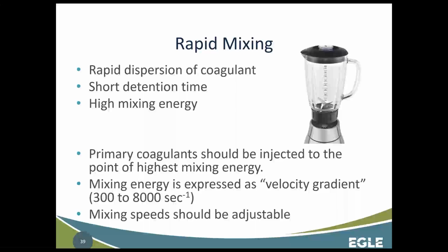However, I would say static mixers kind of fall short on this because it's all dependent on what the flow rate is. Maybe they could be adjustable in the sense that if you have multiple mixers in parallel and you're in a low flow situation, maybe you can turn off one of the trains and force all the flow through one mixer in order to increase the energy. But that's one of the shortcomings of a static mixer, is that you're not going to be able to just walk over to a dial and turn the speed up like you could on a mechanical mixer.